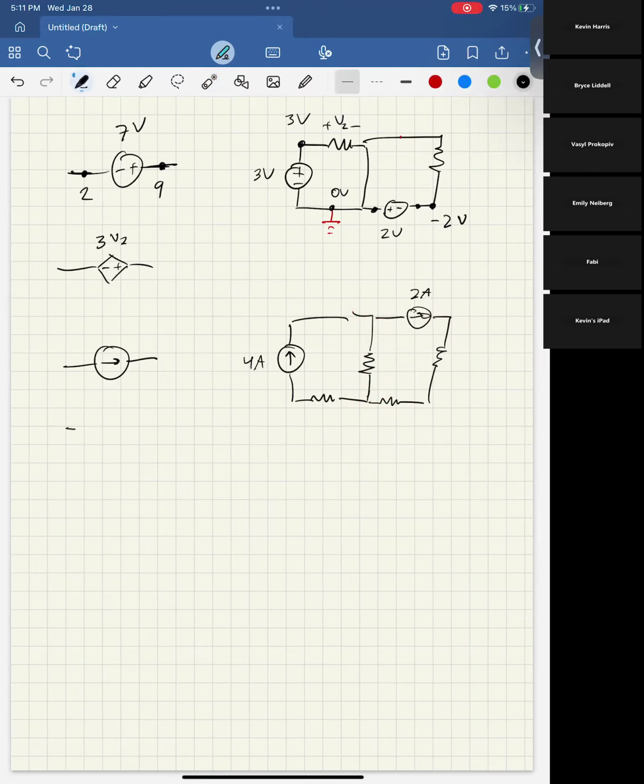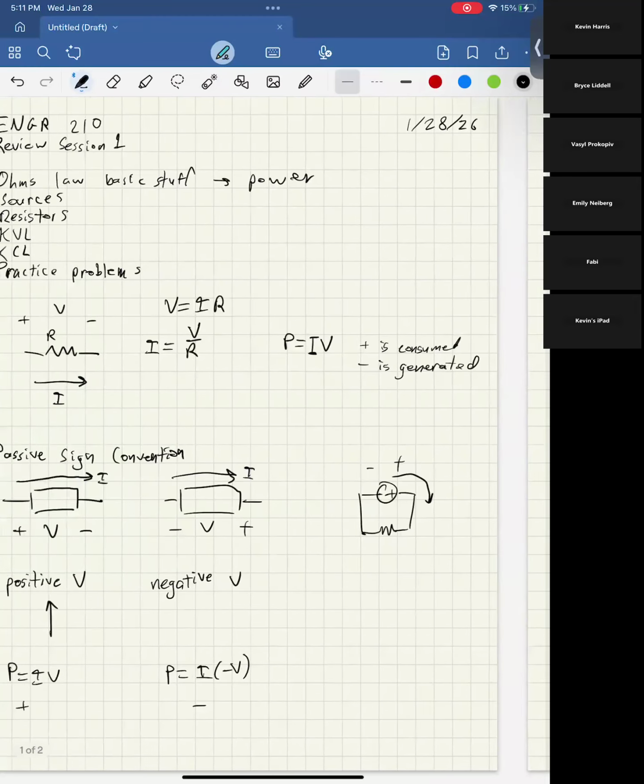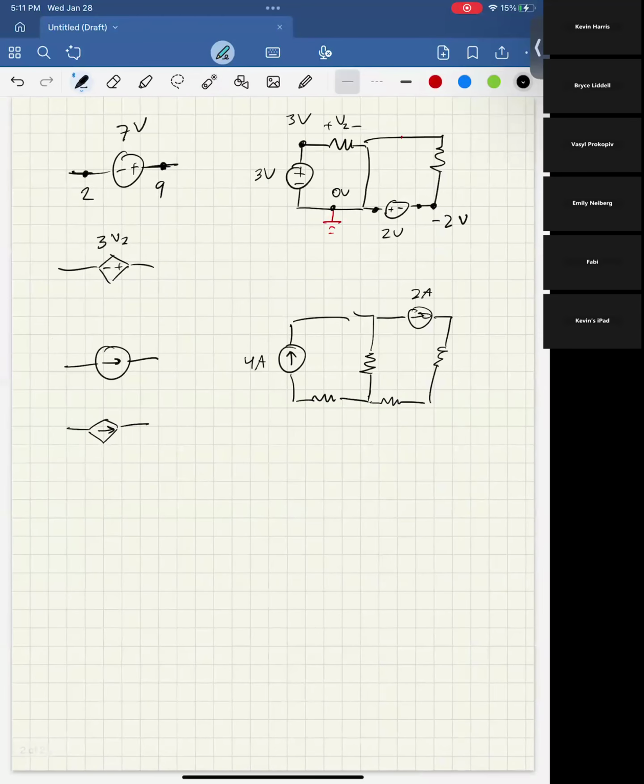Okay, and then likewise, you have dependent current sources, where it's the same thing, just an equation. Okay, then briefly I'll touch on how to combine resistors with each other, because that's something that can be useful. If I have 2 resistors in series and they are R1 and R2, then you can say that this is equivalent to 1 resistor with a value of R1 plus R2.